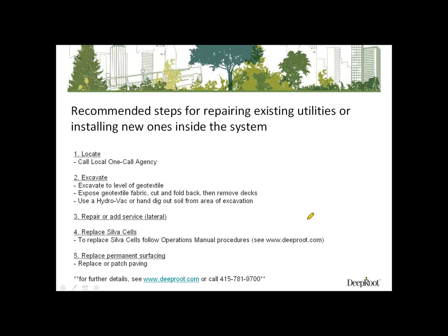First of all, we've laid out some recommended steps for when there is a repair needed or any maintenance when you'll be working near or in the Silva Cell system. And I'm not going to spend a lot of time on it. It's all pretty much common sense, but you want to call your local one-call agency. You want to remove the pavement in the area and excavate down to the geotextile fabric that's on top of the deck. Expose the geotextile fabric and cut that away. At that point, you'll be able to see the deck.